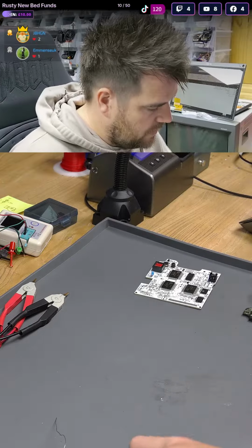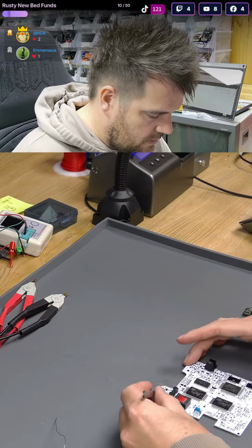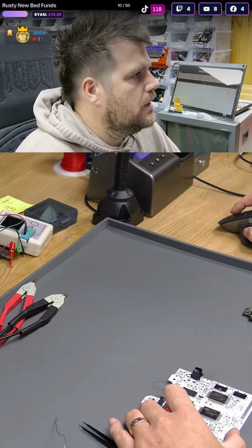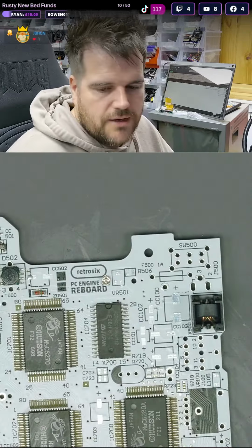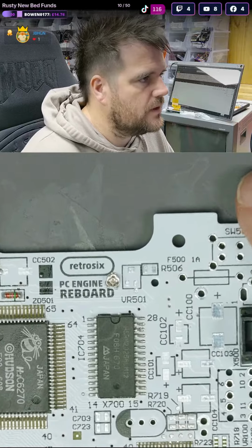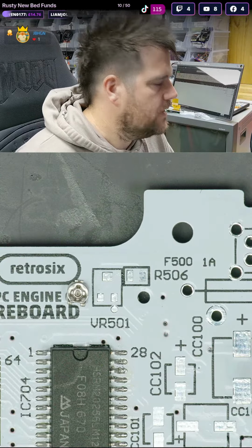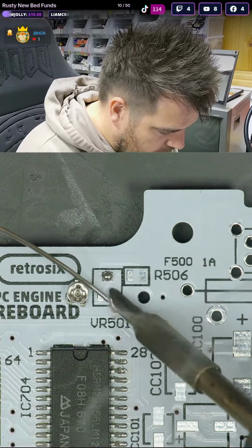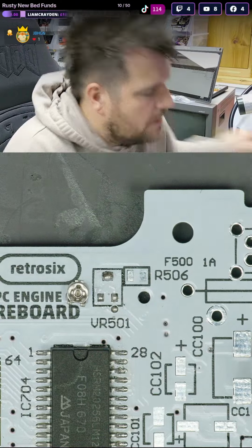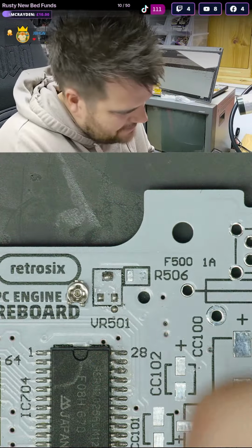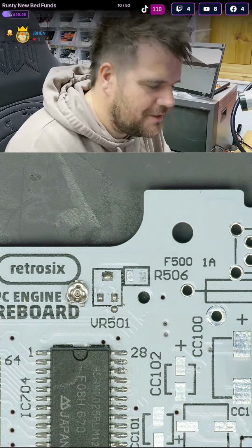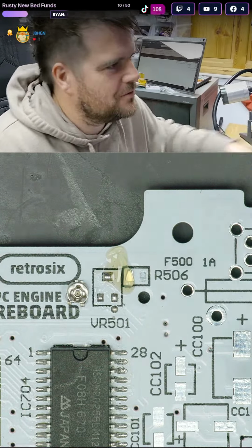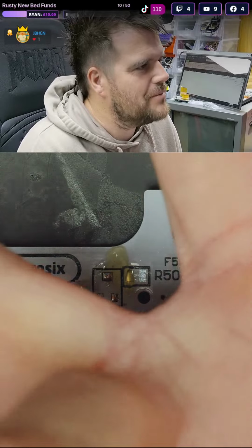And then what we'll do is solder this on our board, and we'll just take it off the customer's board because we don't want to keep looking at things that are still on the board and getting confused if we've done the work or not. These can be hot aired on, so long as you don't take too long, you can melt them. But if you know what you're doing. Just as I say, if you know what you're doing, I flick solder right on my finger. Right in between the grooves of your finger as well. It always goes on the hottest spot.